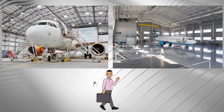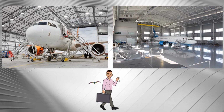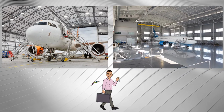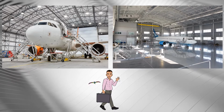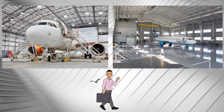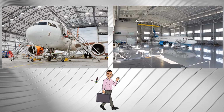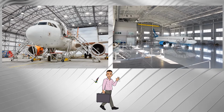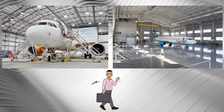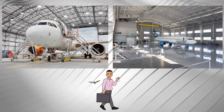Hangars are usually provided with light overhead cranes covering the full area. They are used to handle dismantled parts up to 1 ton weight. Isolated engine hoists up to 10-ton capacity may also be provided. Alternatively, the overhead cranes may be of 10-ton capacity. Conflict can arise between cranes and suspended docking. If a two-level roof is adopted, separate cranage is required in the tail bay.